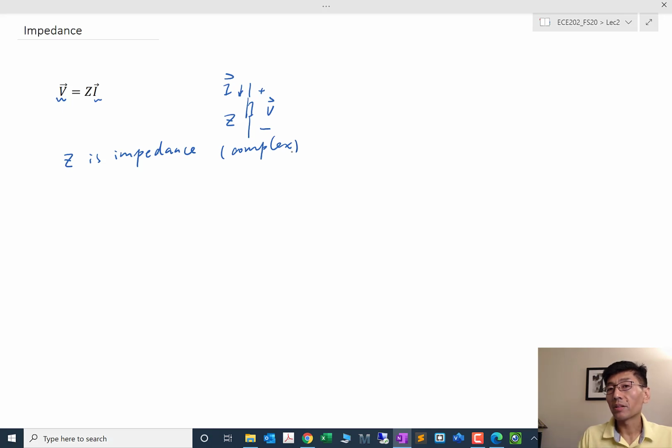But sometimes it's hard to wrap your head around this concept intuitively, right? How does this complex thing really work? The complex number has a magnitude and phase angle, even for the impedance. That means if the impedance is complex, the voltage and current most likely are not going to be in phase, right? So in addition to their magnitudes being different and skewed by the impedance, there is also the phase angle. That's how this really relates back to the signal in the time domain.